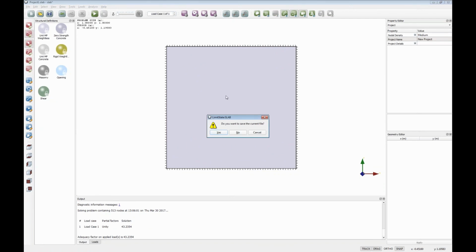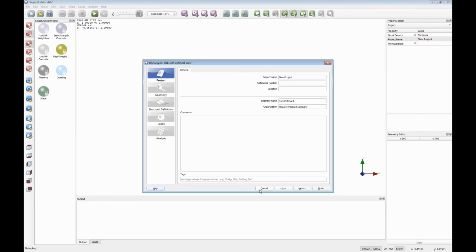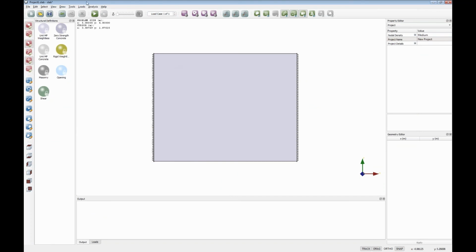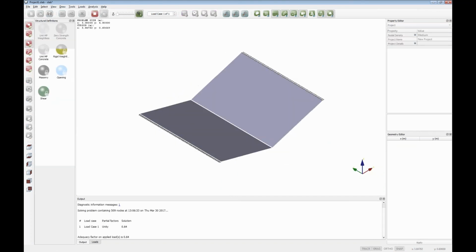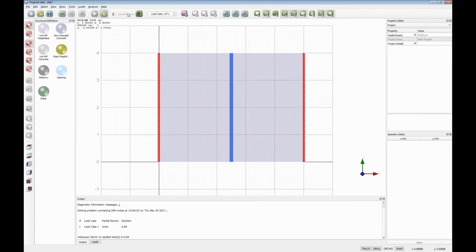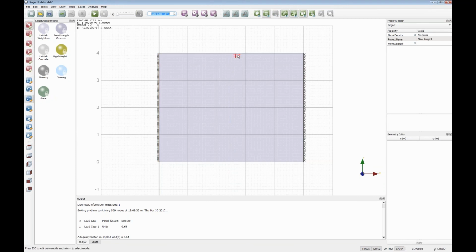So what we can do is very quickly make a new rectangular slab, and if I remove the support from the top and the bottom and make that free, we can solve this problem, and what we'll get is just a single line. So we're getting a folding book type failure mechanism for this particular problem. But maybe we want to provide a support that could come from a wall or something in the middle, and it's relatively easy to do that.